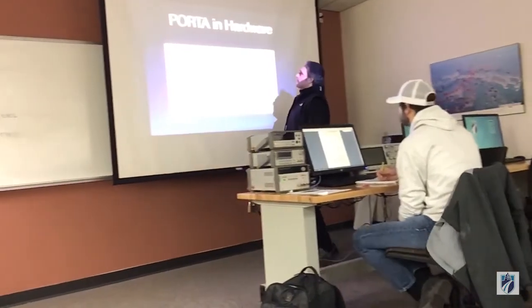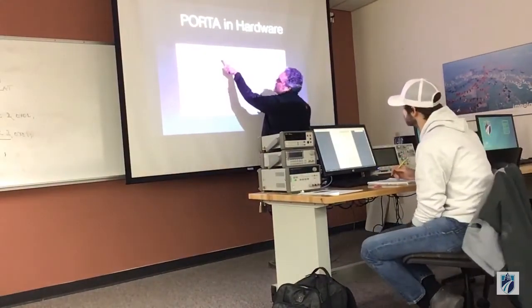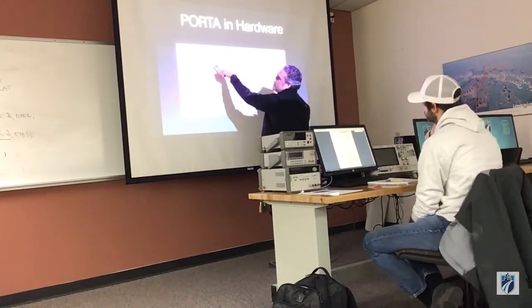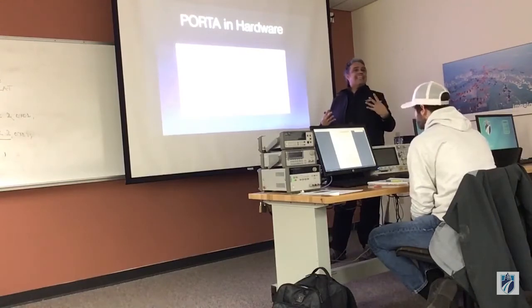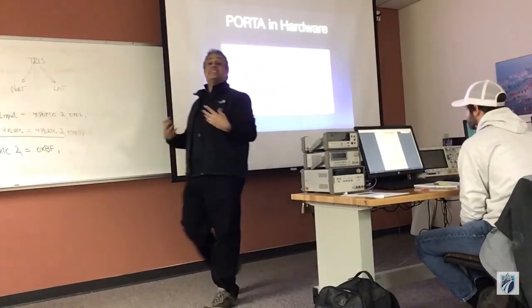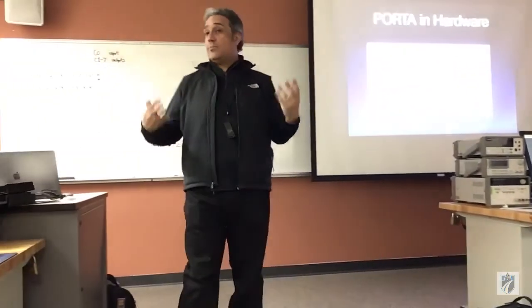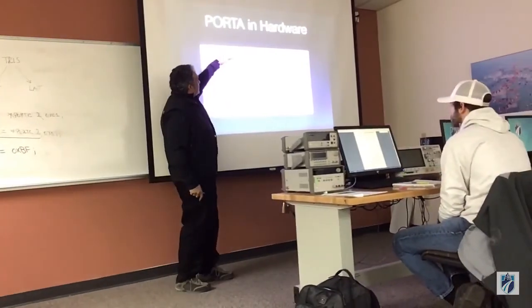All right. So here it is. Here is the pinout. In green, you see the nomenclature for digital pins in the microchip world. So microchip calls anything RA, RB, RC, RD, RE a digital I/O. That is the GPIO, general purpose input-output. However, notice that they are not in sequence.